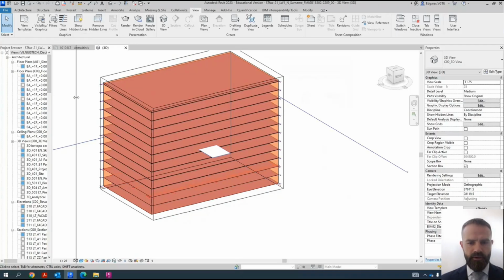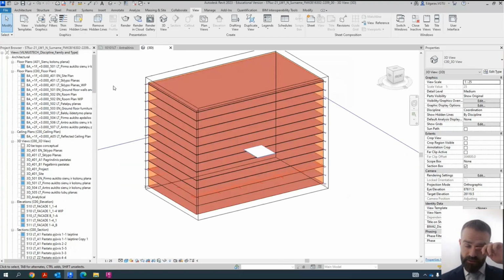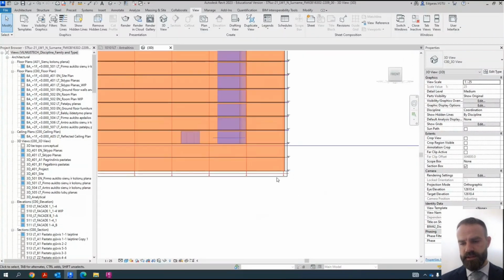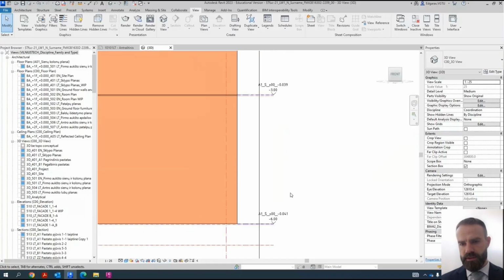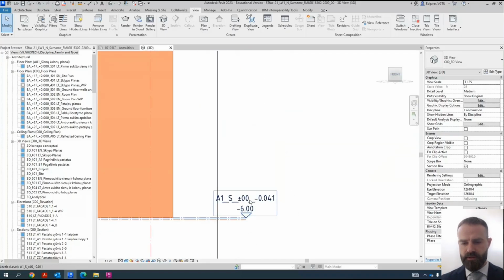And now I will create needed modifications. Before jumping to all these modifications, I should go to the floor plan of my building and do additional checking if my mass object is nicely created. So now for foundation walls, I will jump to this layer.